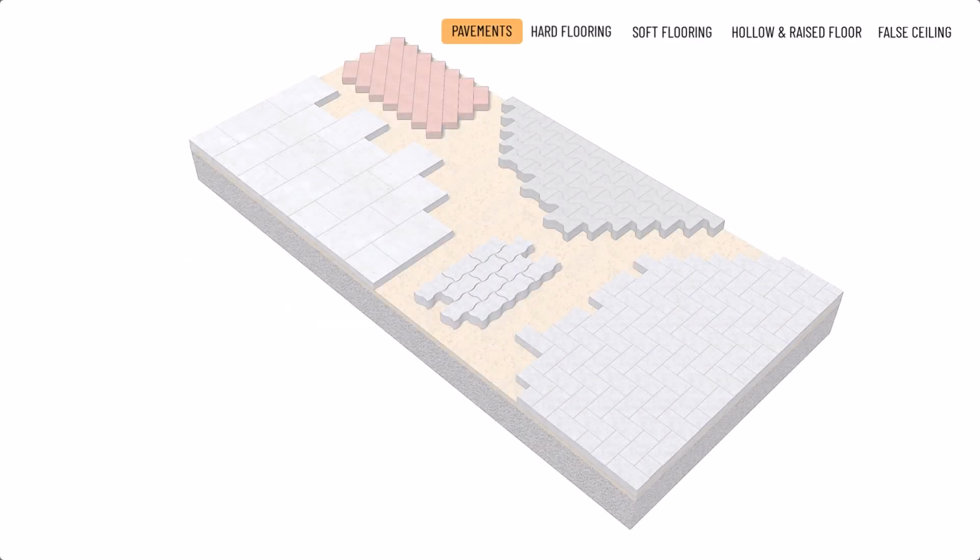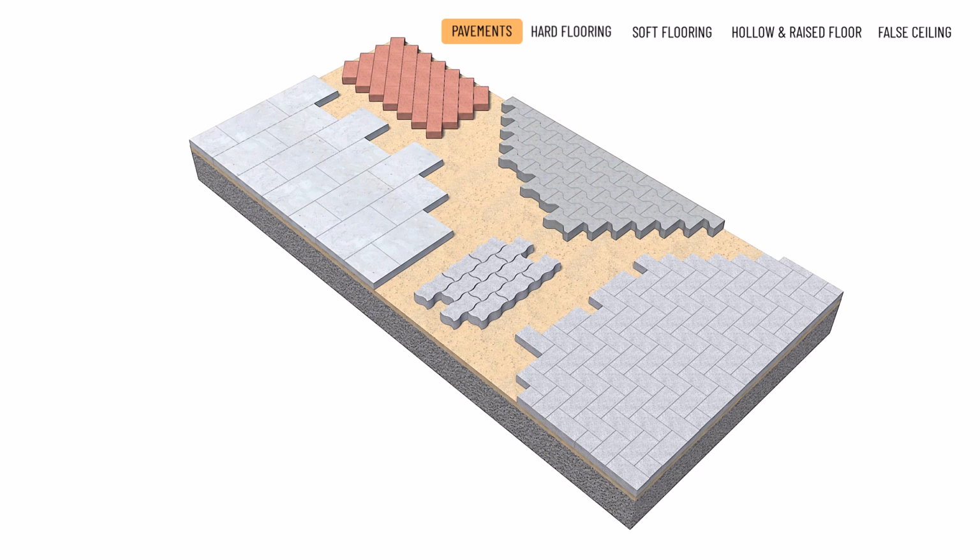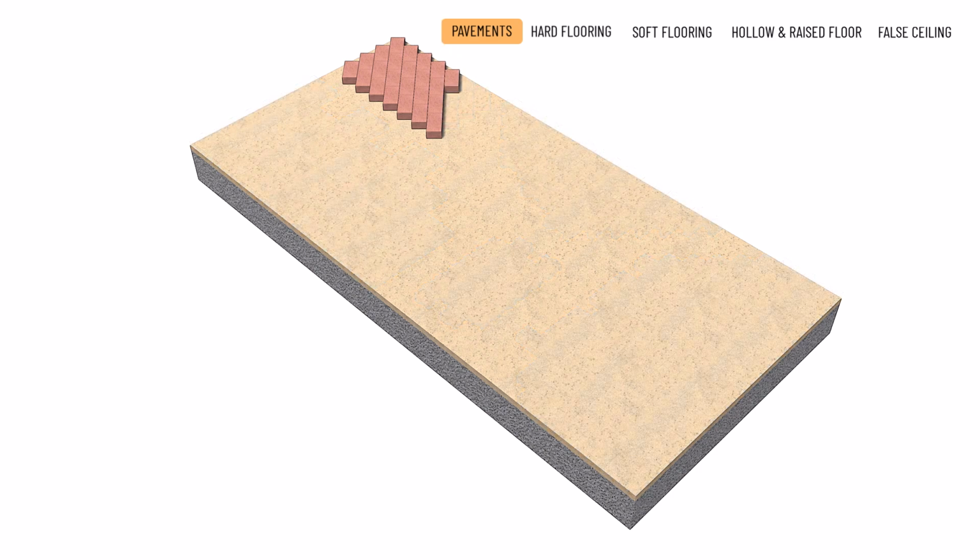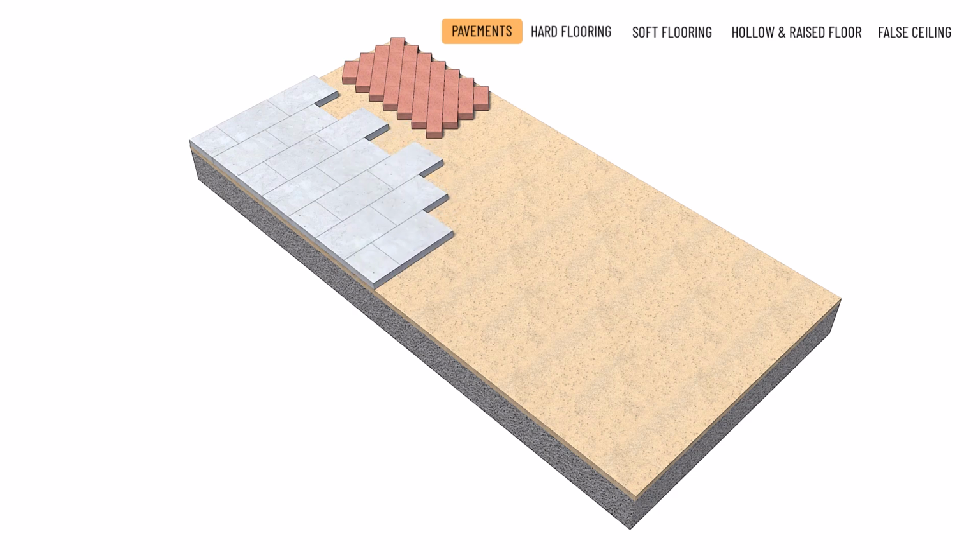Pavements. Pavements around buildings, terraces, parking areas and public spaces are often constructed using small-sized paver blocks. For higher quality applications, such small-sized block pavements may be made of stone tiles or clinker-quality fired bricks. Lower requirements or domestic use may utilize concrete paver blocks instead.